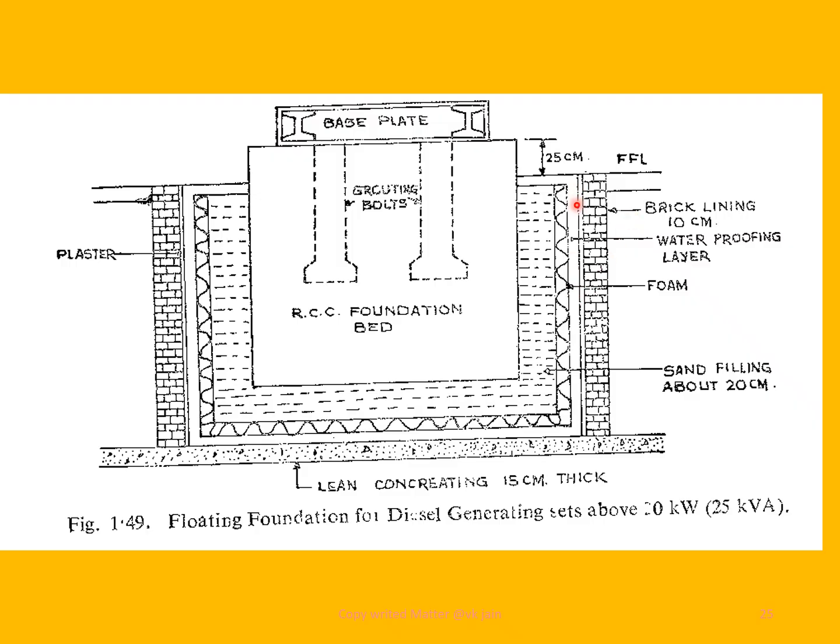Now this is the waterproofing layer, and this foundation is provided above the floor level, finished floor level. The foundation has to be 25 centimeter above.